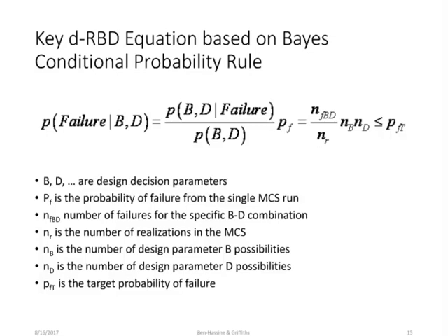So when you do a simulation, it's just one run of this Monte Carlo simulation, and you run the simulation for all the foreseeable combinations that you want to consider for this design. For example, your foundation, let's say you think it's going to be between 5 and 12 feet in width or something like that. So you can pick 5, 6, 7 to 12, and you're going to pick uniformly from those selections.